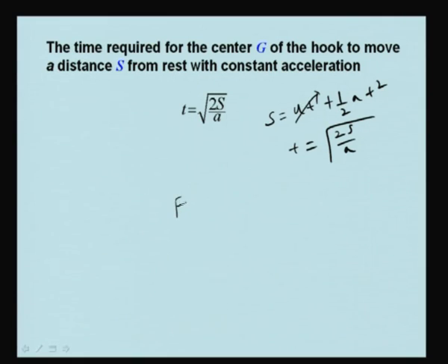So by applying these basic equations, F net is equal to mass times the acceleration of the center, that is the vector equation, and also sigma M_0 is equal to I_0 times alpha. By applying these equations, we can solve any problem of kinetics in plane motion.